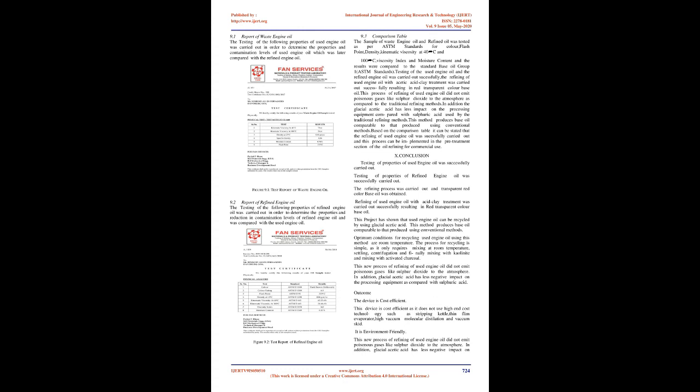9.3 Comparison table. The sample of waste engine oil and refined oil was tested as per ASTM standards for color, flash point, density, kinematic viscosity at 40°C and 100°C, viscosity index, and moisture content, and the results were compared to the standard base oil group 1, ASTM standards. Testing of the used engine oil and the refined engine oil was carried out successfully.